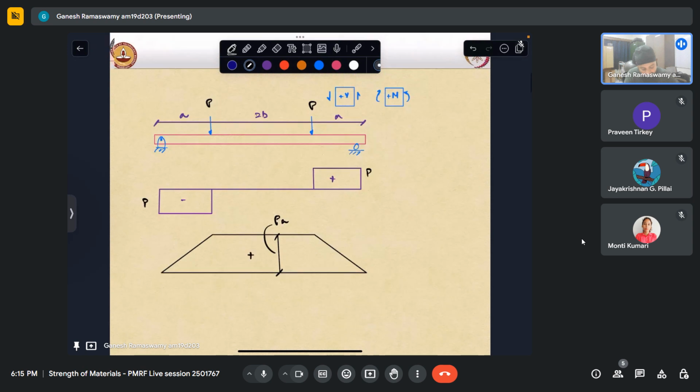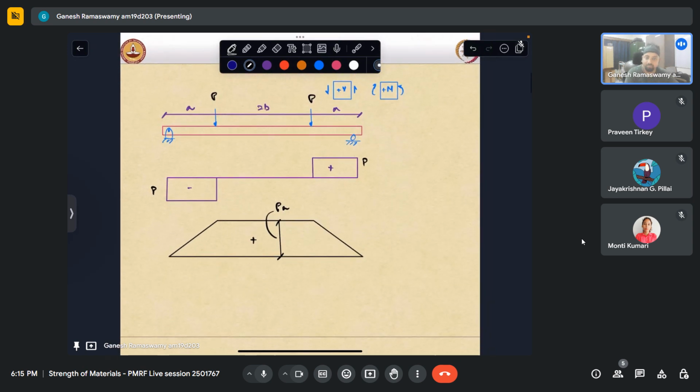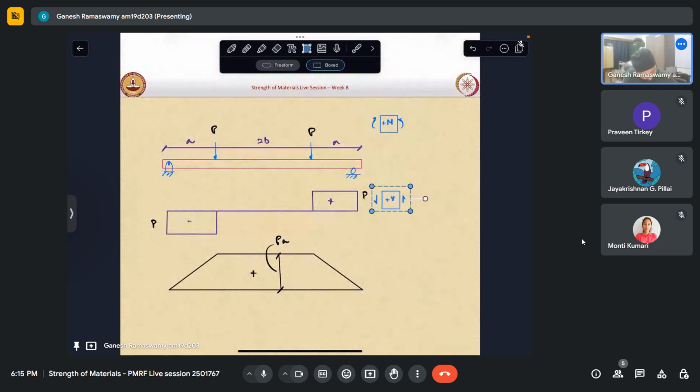So in a beam like this, a four-point bend beam, essentially there is a reaction which transmits a constant shear force in this portion. Then it is nullified, so for this portion there is essentially no shear force acting. Then we have a drop in the shear going back, and the reaction brings it back to zero. So we have the shear force diagram like this with my sign convention, and my bending moment diagram is like that.